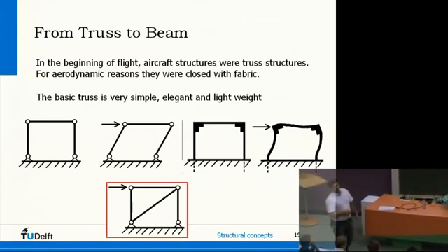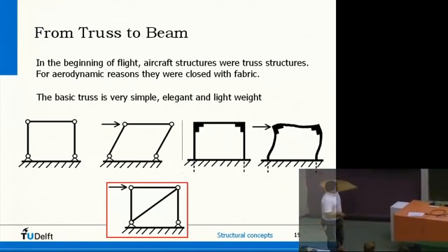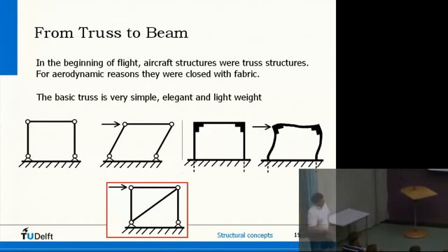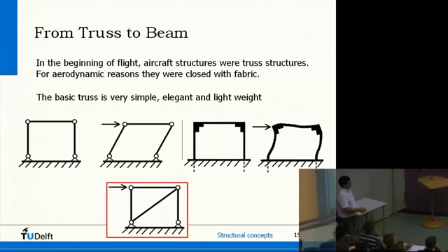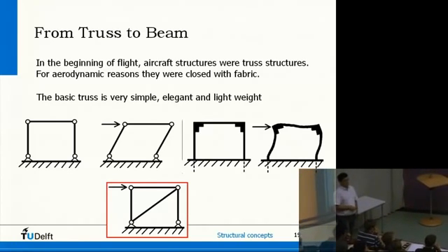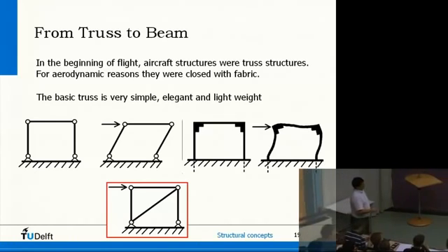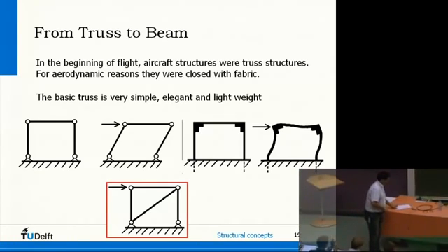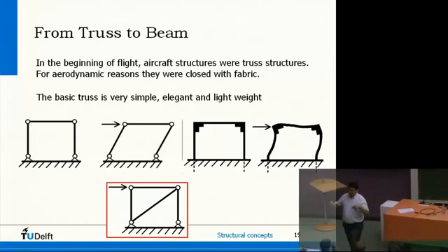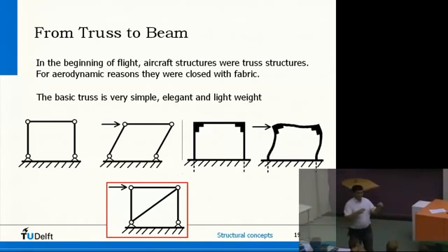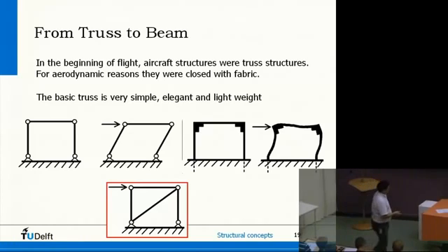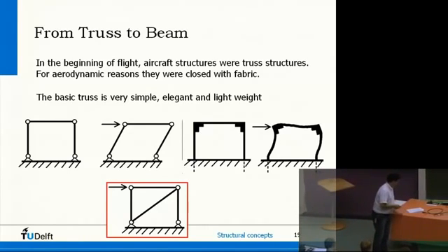So a more elegant way to do it is to put an additional element in there, another beam, another bar, as you can see here. And this is sufficient. Now we do have a statically determinate structure. Well, if you look at truss structures, they are built from elements like these. This is a starting element, and building up, you can continue and make your truss structures.